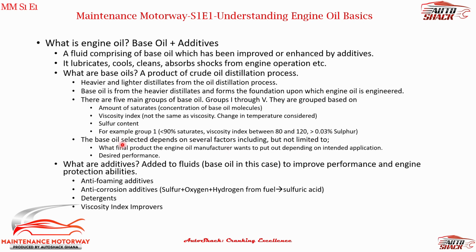The base oil selected depends on several factors, and just 2 of these factors are what kind of engine we're going to be running this oil in. For instance, if we're just going to be running the engine on a construction site, on a big truck that's going to be running all day, we're going to select the base oil and additives based on that. And also if this is a high performance vehicle or an everyday driver, all those factors go into what kind of base oil is selected.